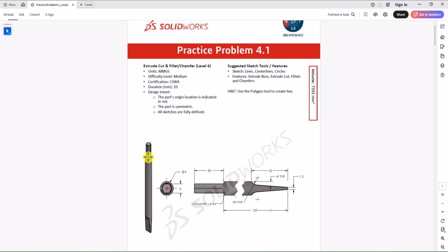My preference is to focus on the cylindrical section first. I'm going to make this part. Then I'm going to make the bottom section. And finally, I'm going to use a polygon shape, make this top feature, and I'm going to use extruded cut to make the final feature in this geometry. So with this introduction, let's jump into SolidWorks and start modeling this part.